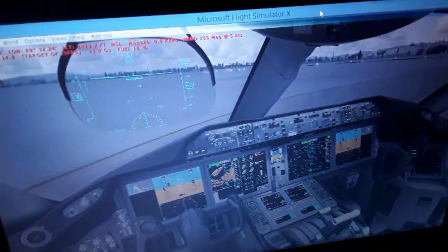You're also going to see that we have the flight director crossbars for manual guidance of the aircraft and the autopilot crossbars for automatic guidance of the aircraft. We also have the angle of attack of the aircraft as it flies, and the flight mode annunciator with the autopilot and the autothrottle, and later the vertical navigation modes. We also have the horizontal situation indicator that displays the magnetic heading and track, and also the flight plan. We can create a flight plan using the flight management computer over here.